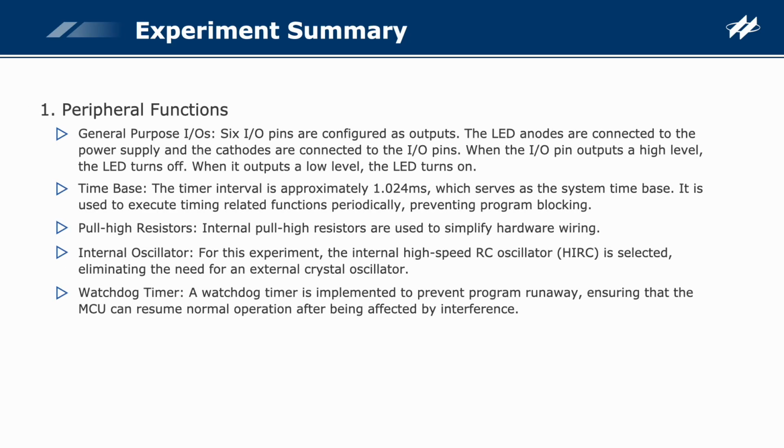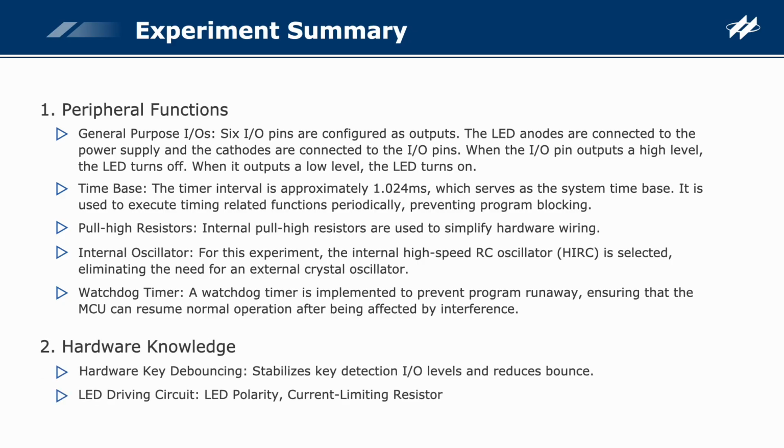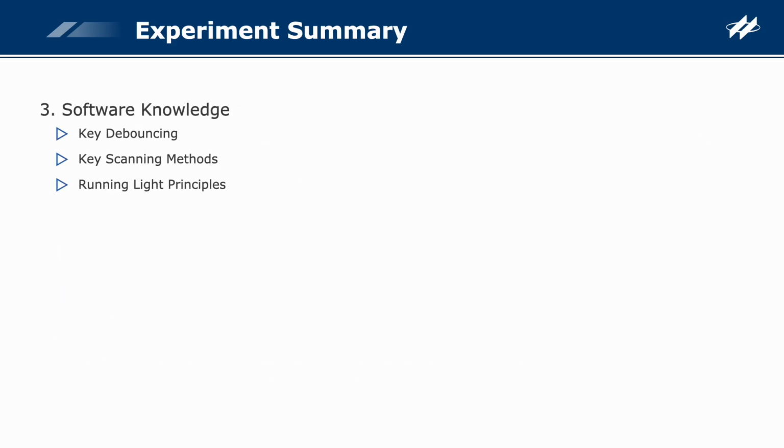Experiment summary. This comprehensive experiment utilizes multiple peripheral functions of the HT8 MCU, including the following 5: the general purpose I/O, time base, pull-up resistor, the internal oscillator, and the WDT. The hardware knowledge includes hardware key debouncing and LED driving circuits. The software knowledge includes key debouncing methods, key recognition principles, and the running light implementation principles.